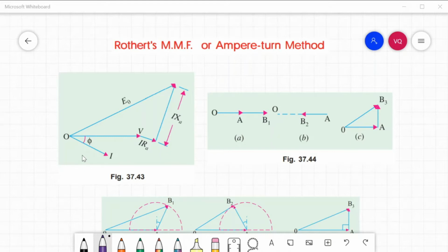Therefore, the power factor on short circuit is almost zero lagging, and the field ampere turn are used entirely to overcome the armature reaction, which is wholly demagnetizing. In other words, the demagnetizing armature ampere turn on full load are equal and opposite to the field ampere turn required to produce full load current on short circuit.